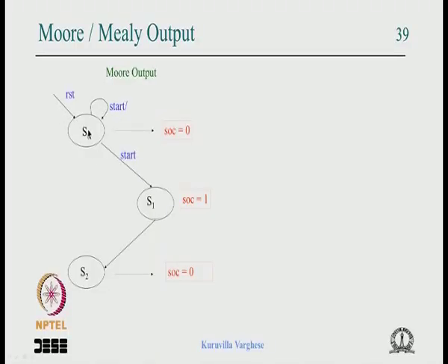There the state machine was generating a start of conversion pulse. So that is a scenario. Let us look at that state diagram. So this was the state diagram. Let us go to the slide. If you remember, I hope it was simple enough. At power on we come to a state, and we were waiting for the start signal from the host CPU. As long as the start was low, we remained in this state, and the start of conversion pulse was 0.